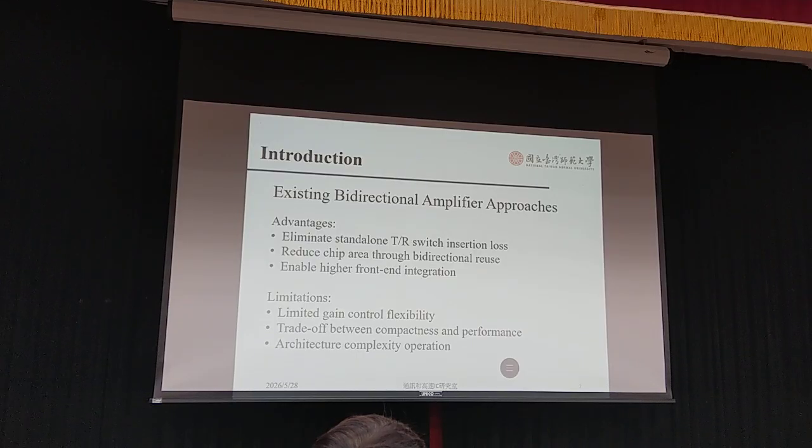So, from previous works, we can summarize several advantages. First, they reduce chip area. Second, they improve integration. Third, they avoid extra switch loss. But there are also limitations. Number one, gain control flexibility is often limited because many bidirectional architectures strongly rely on a shared signal path. Once the transmit and receive functions are tightly coupled, adding independent gain tuning becomes more difficult.